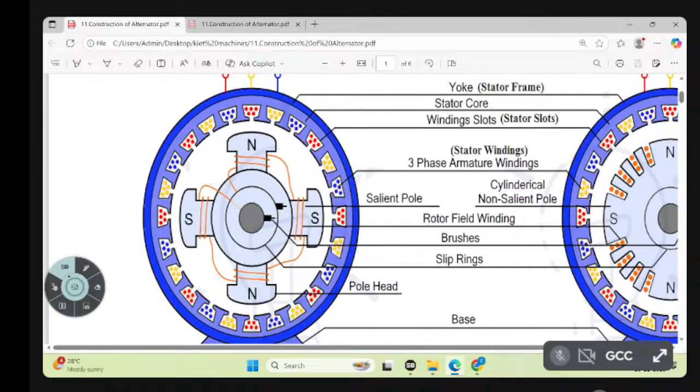So this is the rotor. North pole, south pole, north, south, north, south. So why do we wind this one? Because it is not a magnet. We are making it a magnet. So that's why we wind the winding. So one terminal, like this. First terminal, plus terminal, clockwise, anti-clockwise, clockwise, anti-clockwise, and second terminal, minus terminal.